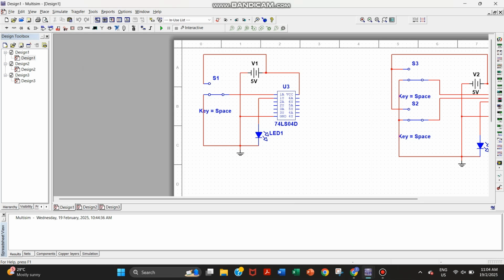The circuit design in this video will mainly have the positive terminal and negative terminal, where 5V is applied across it. They are also connected to the switches, which determine the output to be 1 or 0. Positive terminal for 1, negative terminal for 0. There is also the power supply, which is connected to the top VCC pin, as well as the bottom corner GND pin, which is connected to the ground. The input from the switches will go through each of the following gate IC chips to verify the output.